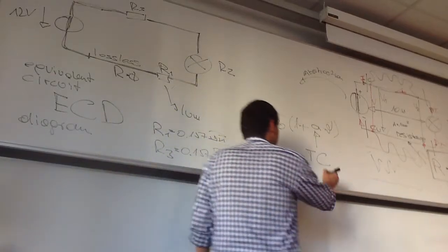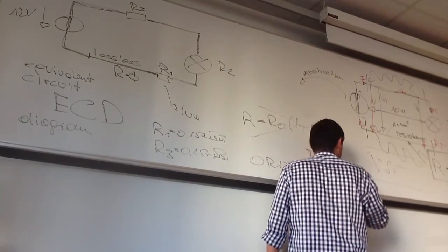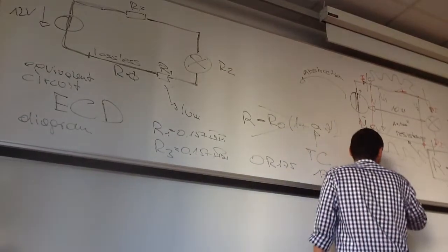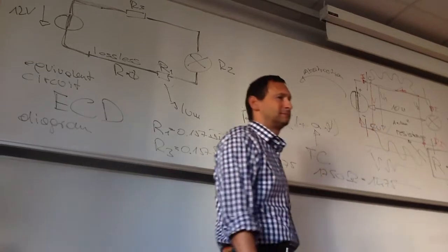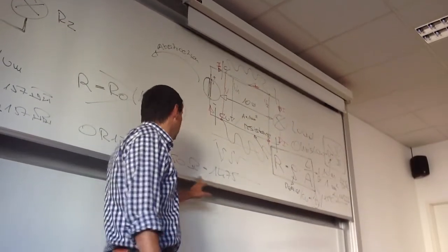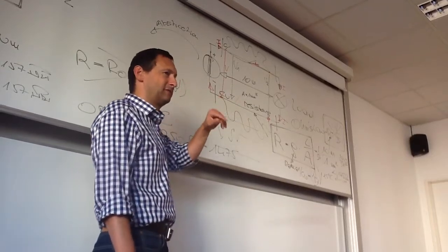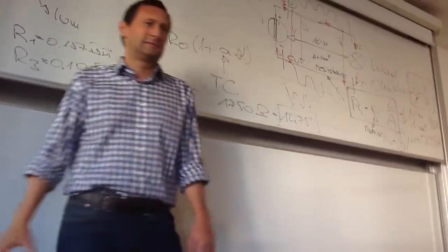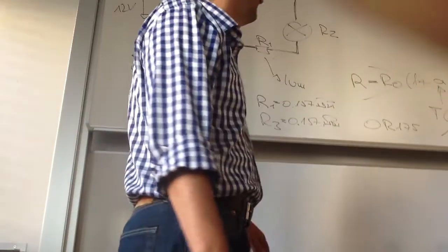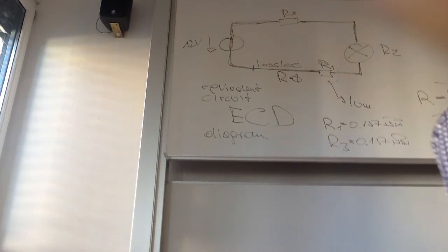Also, if your resistance is 1075 ohms, then you write 1K075. K is 1000. Or if it's 1,750,000, you write M: 1M75. So if you look into a circuit diagram, you will never see a decimal point because it will get lost. At least in the old times where you had the circuit diagram on paper.